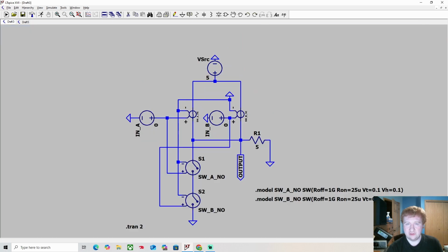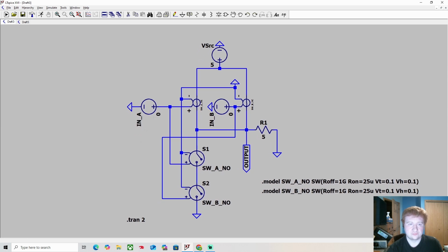If I were to now turn one of these voltages on, we can go through that particular step. So if I turn this to 5, so now that we have 5 volts coming to this switch, it now activates this switch, meaning that it will flip open. So think of 5 as closing the switch, but on a normally closed it would open the switch.